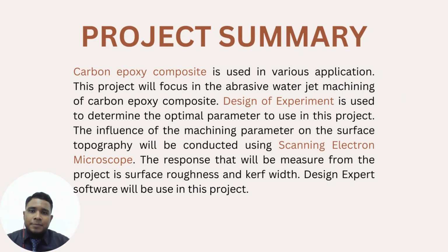Okay, for the project summary, carbon epoxy composite is used in various applications. This project will focus on the abrasive water jet machining of carbon epoxy composite. Design of experiment is used to determine the optimal parameters to use in this project. The influence of the machining parameters on the surface topography will be investigated using a scanning electron microscope. The responses that will be measured from the project are surface roughness and curve width. And Design Expert will be used in this project.